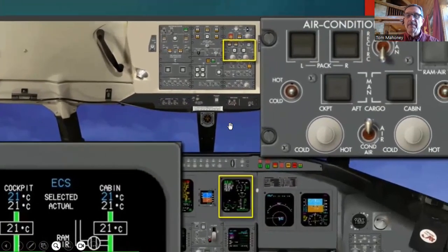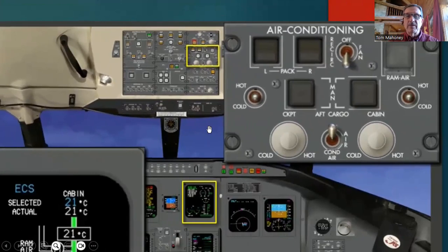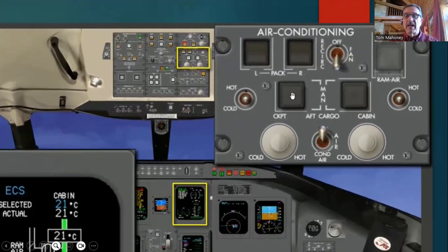So these two black buttons right here in the middle, if you select those buttons to the lit position, you are going to turn the system from auto to manual. If you turn it from auto to manual, you'll have to operate the valve using a toggle switch right here on each side. And if you remember what that toggle switch operates, I'll just show you.